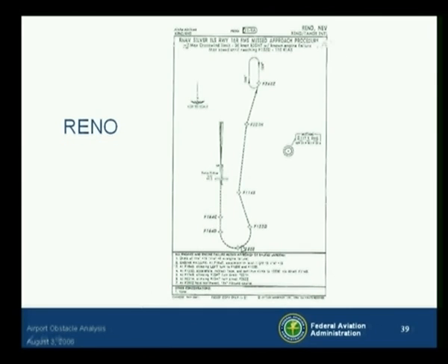It consists of these several waypoints that basically, after the runway is missed, bring the airplane around for a rather sharp left-hand turn, because the hills around Reno are out in this area, and the airplane on the autopilot, engine out, or in this case all engines operating, flies the same procedure. Notice the max crosswind limit is 30 knots, and the max speed until reaching the northmost waypoint to get you straight. In other words, the max speed during this turn is 170 knots.